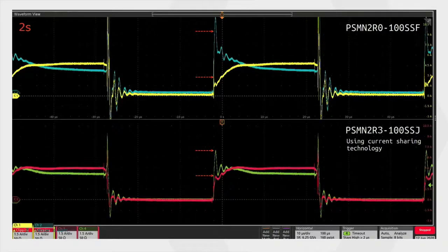Now, another very interesting point is that these dynamic responses that you see here are always fixed regardless of frequency and duty cycle. So these spikes, if you were to increase frequency, they wouldn't change. What would change is the steady state region at the end there, and they would come closer together. Now we have a demo video showing this effect on screen, so it's a bit easier to follow. So please have a look at that one as well. Next slide, please.